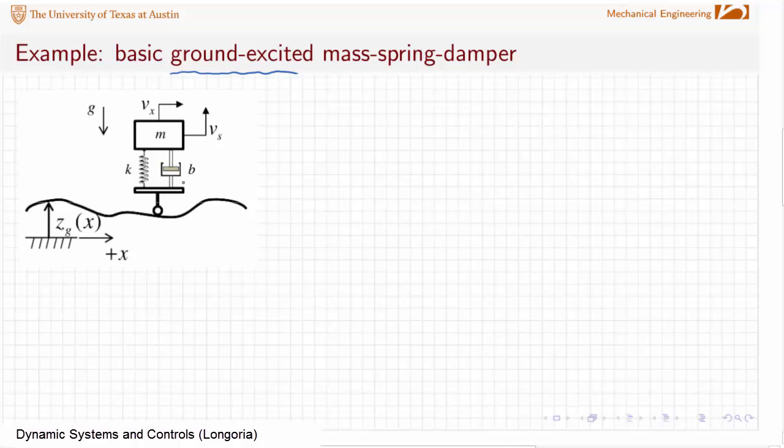Okay, so how would we go about modeling this system with a bond graph? Now, I'll assume that you could build a free body diagram and take a straight vibration model approach, but again, we're trying to practice bond graph modeling. One thing that you can do is start off with the mass and put a 1 there because we know we have a velocity associated with that sprung mass. So I'm going to put a mass here.